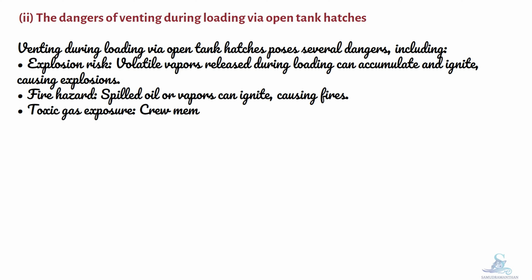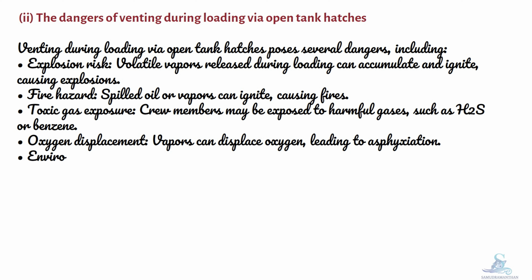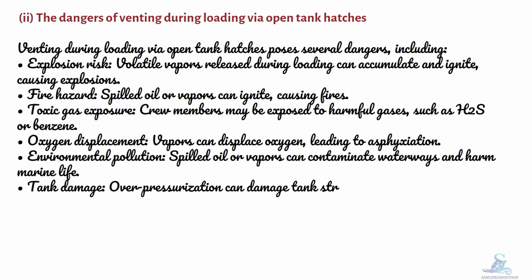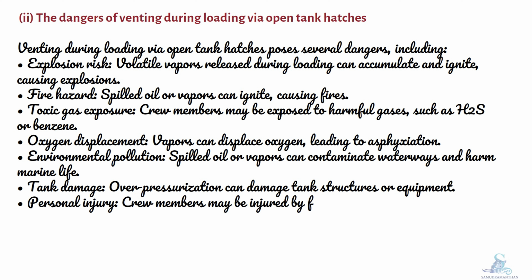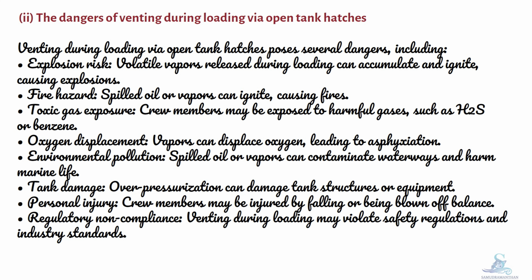Toxic gas exposure. Crew members may be exposed to harmful gases, such as H2S or benzene. Oxygen displacement. Vapors can displace oxygen, leading to asphyxiation. Environmental pollution. Spilled oil or vapors can contaminate waterways and harm marine life. Tank damage. Overpressurization can damage tank structures or equipment. Personal injury. Crew members may be injured by falling or being blown off balance. Regulatory non-compliance. Venting during loading may violate safety regulations and industry standards.